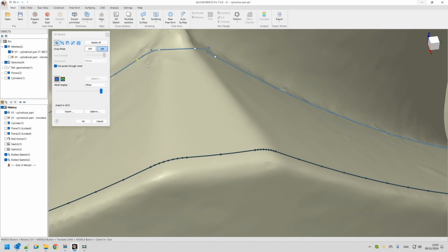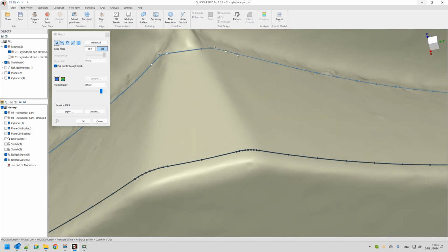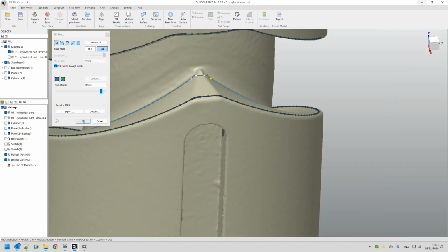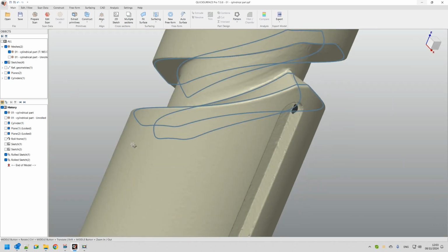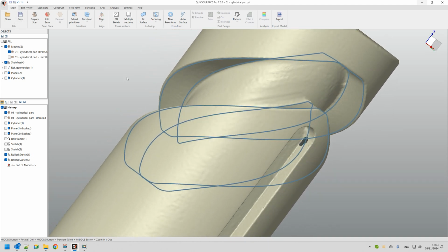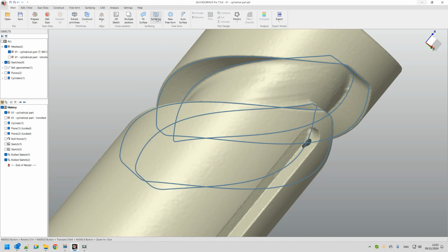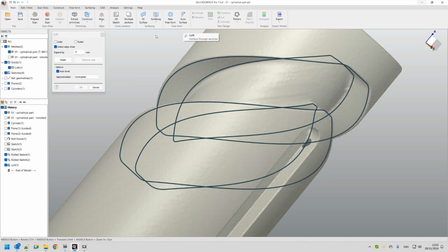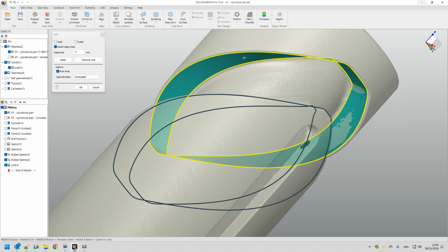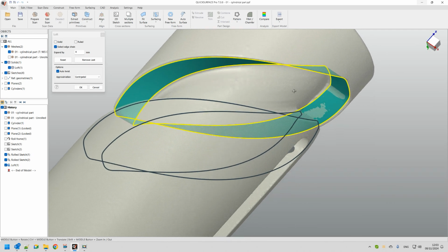As you can see, we use the unroll command very accurately and precisely to recreate the shape that I needed. So this is what we have right now. It looks a little bit of a mess. Let me save it, but it should work perfectly fine because I'm going to use the loft command, pick this profile and the other one, and it will create the surface for me, nice and smooth.